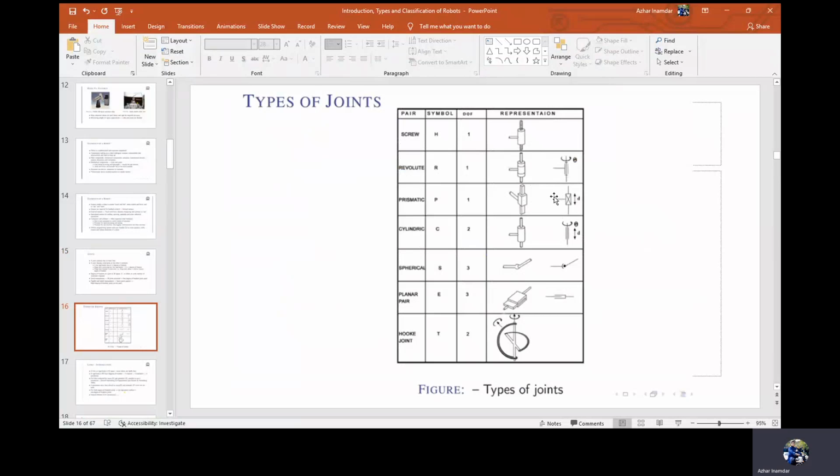Okay, so this is a cylinder, and next one is a cylindric joint, which is sometimes seen in closed loop mechanisms. Here the theta rotation and the sliding d are not related. There is no pitch, they are independent. As I said, you can also have a spherical joint. It has 3 degrees of freedom. A spherical joint is nothing but a ball and socket joint.